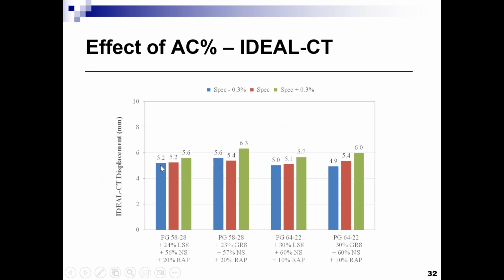This is the displacement that corresponds to the location where we calculate the post-peak slope. And again, it should increase because your material is becoming more ductile. If you want to think of the strength and the displacement as anything, I would use the Marshall flow and stability. So the stability is more like you're capturing the strength of the asphalt mixture, and with the flow, you're capturing the deformation. So you can see again, when you put more binder, you get more deformation or more flow in your asphalt mixture.